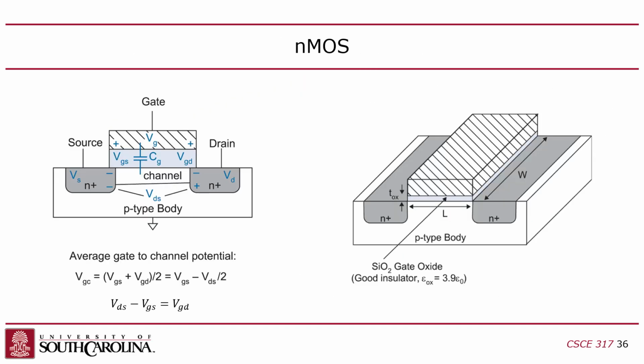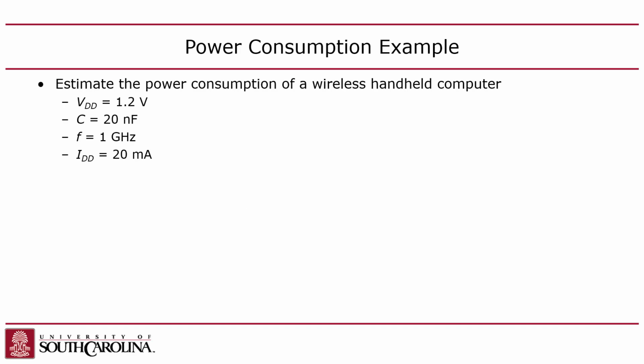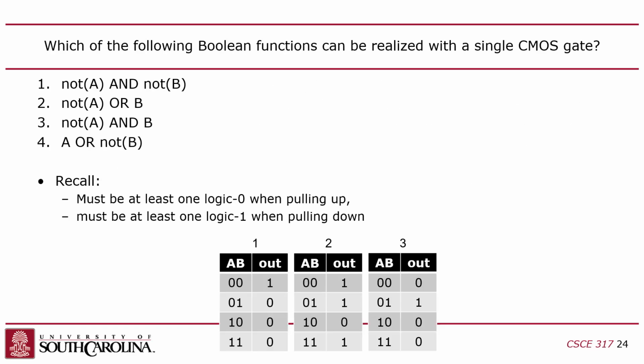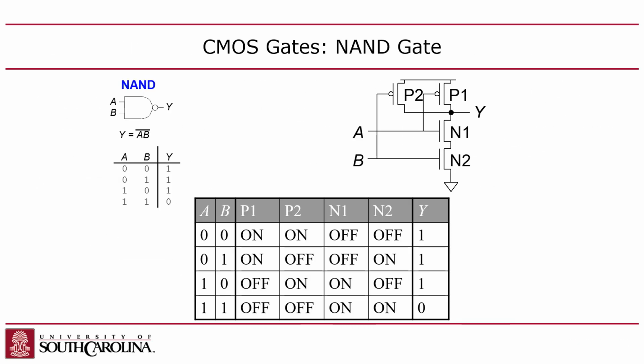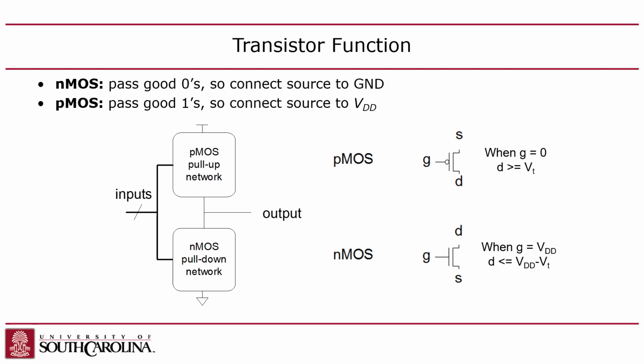For the NMOS, sorry, I always forget which one is which there. Yeah, so with the NMOS, its drain is on the top and source is on the bottom. So it's drain source, right? And on the PMOS, the source is on the top. So the source is going to be connected to the ground, right? And the drain is going to be the output on an inverter.